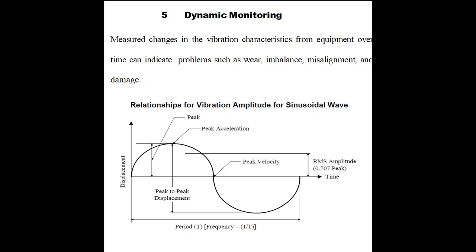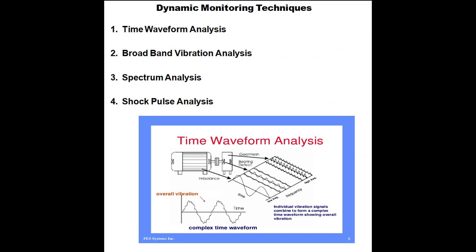But if at certain points these values go high beyond the permissible limit or go down to the lower side of the permissible limit, you should always check the machine. So if we get continuous data like this, we can easily predict the performance of the machine. We can check the part of the machine if we get any variation in this kind of plot. So this is why dynamic monitoring is important.